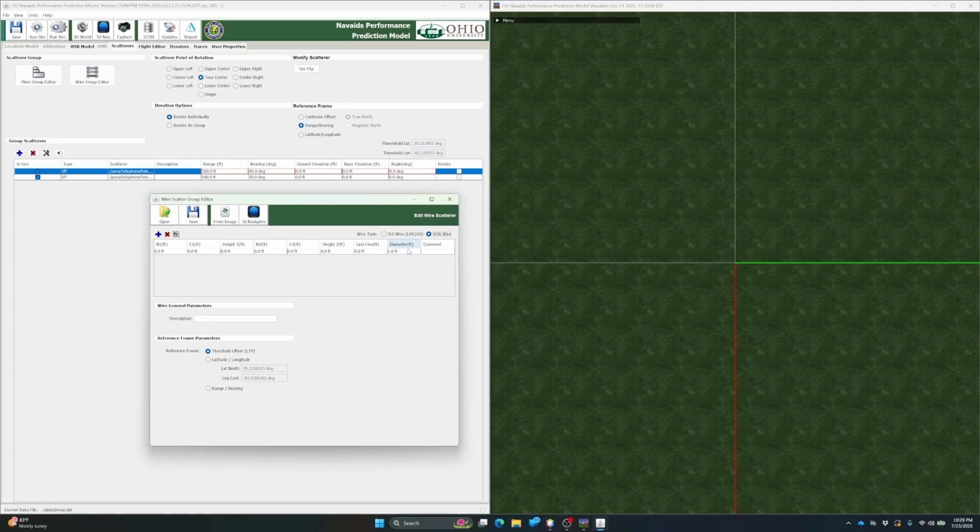If it is more than 1/10 of a wavelength, then you probably should start thinking about using plates instead. So if it's like a bundle of wires, maybe use a plate. So I probably shouldn't make the default for this 1 foot. I'm going to say 0.1 foot.